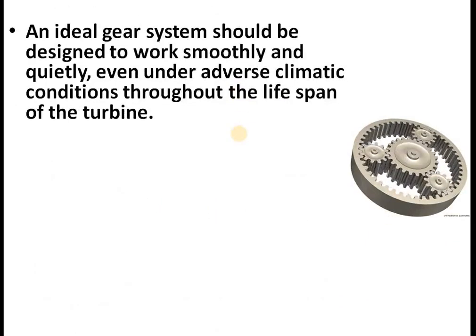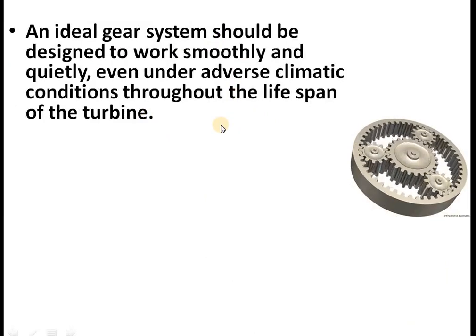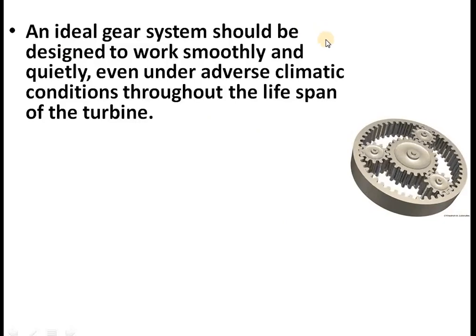An ideal gear system should be designed to work smoothly and quietly even under adverse climatic conditions over its lifespan. For that, proper lubrication is given, because every now and then you cannot open the nacelle by climbing up a windmill. It is not very easy.